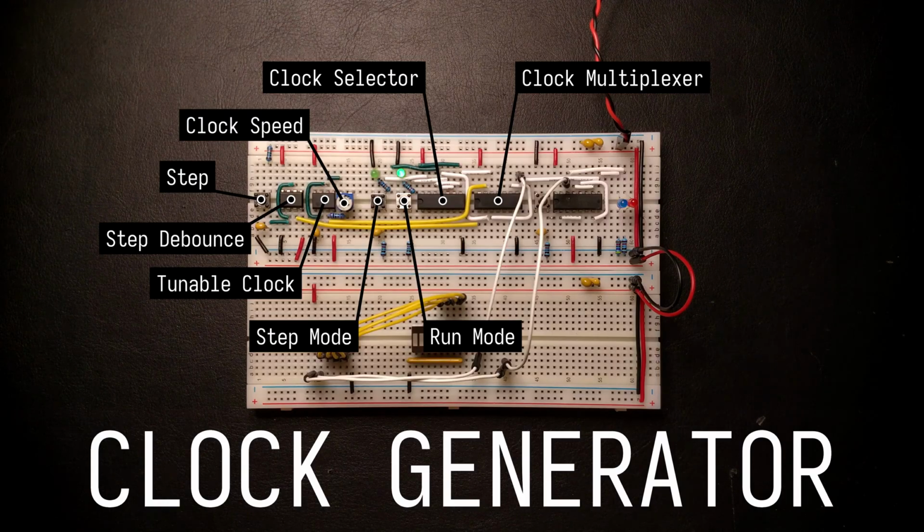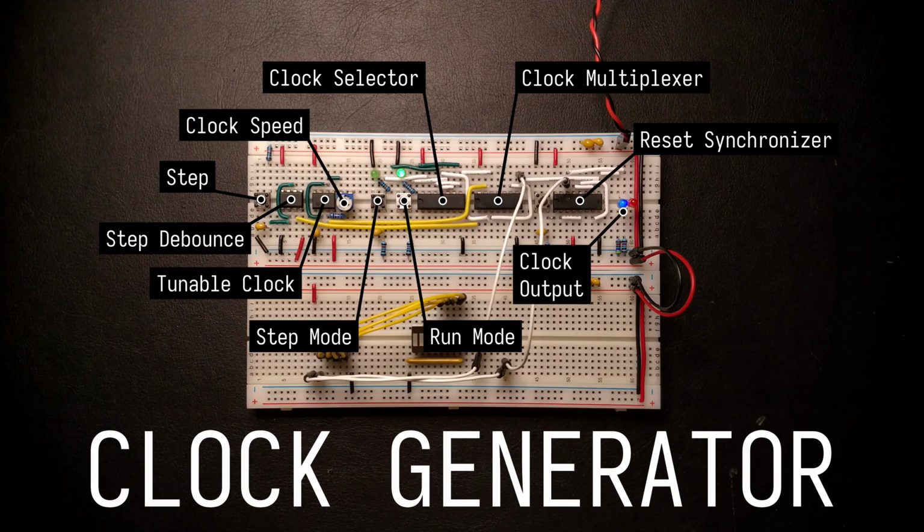And as a final consideration, we've looked into generating a clean reset signal in this episode, and added this reset synchronizer over here, which is basically just a chain of flip-flops that keep the CPU's reset line active for a fixed number of clock cycles, and, importantly, releases the reset at a proper point in time. As a result, the breadboard produces a clock output, indicated by the blue LED here, and the reset output, indicated by the red LED.